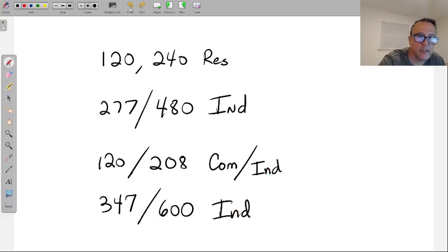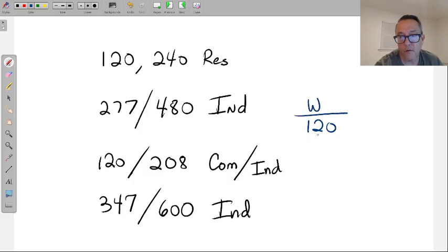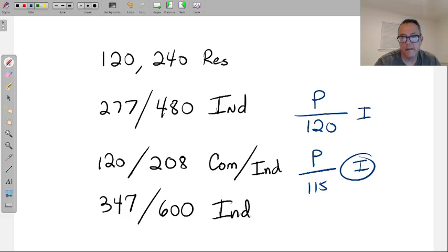So these little fluctuations in voltages are common throughout all voltages. In fact, you guys can try that now with the meters that you have. Turn them over to voltage and start to plug them into outlets, and you'll see the numbers are not 120. Now, can they be? Sure, but it's very unlikely in most cases. So it's an Ohm's law thing. If I divide wattage over 120, I'm going to get a specific amperage, or power. I shouldn't say wattage when we're talking Ohm's law, but that's what it is. If you make that 120 115, that's a different number for amps. It just is.